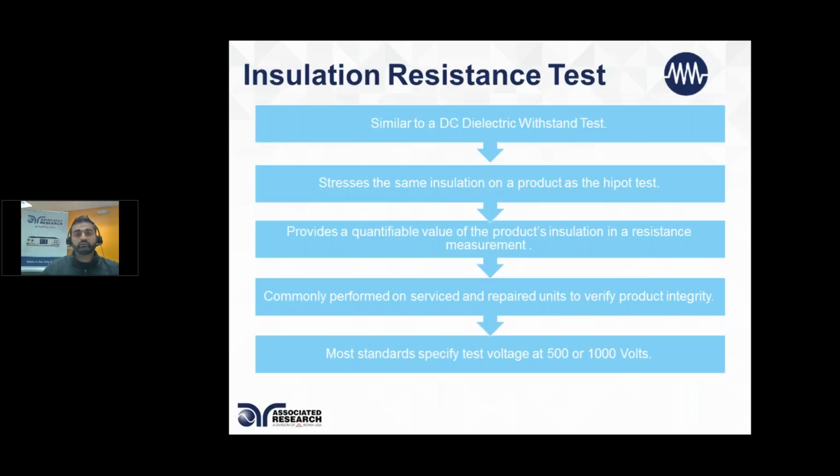At that point, what it tells you is that this motor has reached the end of the life cycle for the insulation part. So either remove the motor, put a new motor in, or service this motor to make sure the insulation is back up to proper levels.